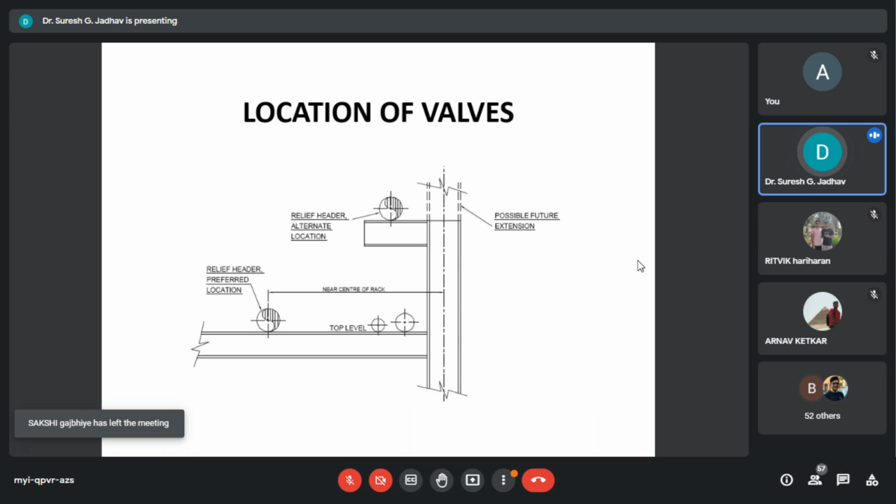If both ends of a line are lower than the bottom tier, the line should run on the bottom tier of the rack. The elevation of the lines can be influenced by the valves and instruments' location. Access platforms are required to be provided if valves are to be placed on the top of rack levels. The consideration is the location of lines with orifice runs.